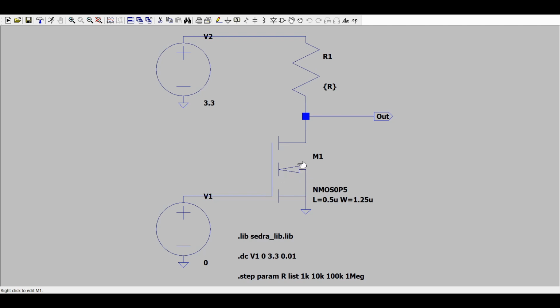And so, depending on how big or small this FET is, that changes what a suitable value for this resistance R is here. Notice that for this MOSFET, and this is typical in an older CMOS chip, I've actually specified the length and the width of the gate. That will be more meaningful in a subsequent part of this video series. Anyway, let's go simulate this now.